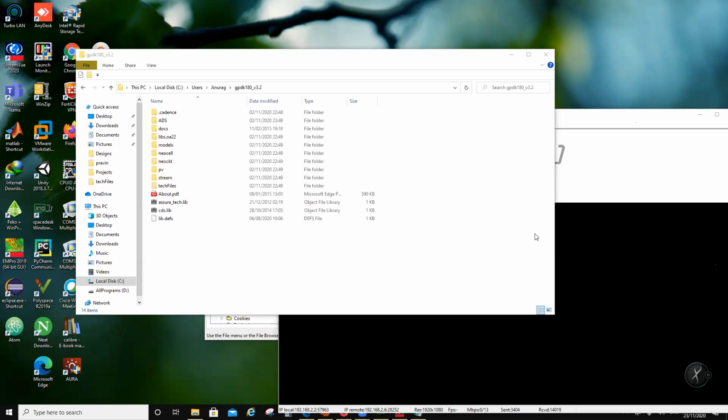And then the surface currents, for example, an antenna where the back plane is ground. Those ground currents are very important. If that is fudged, then the antenna will not be accurate, in the sense that it will show a lot of back lobes in momentum. As soon as you simulate this in EM Pro, you will see that those back lobes were not there. This is because the ground distribution is an approximate one.